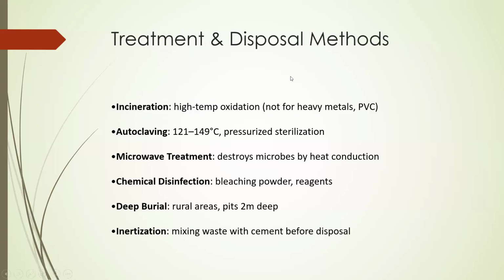Treatment and disposal methods. Before its final disposal, biomedical waste must be disinfected. Anatomical waste can be disposed of by deep burial. Syringes are to be cut and chemically disinfected with 1% bleaching powder solution at the source of generation before final disposal into sharp pits. Infected plastics are to be chemically disinfected or autoclaved, shredded and recycled, and sold, before final disposal into the municipal dumps.